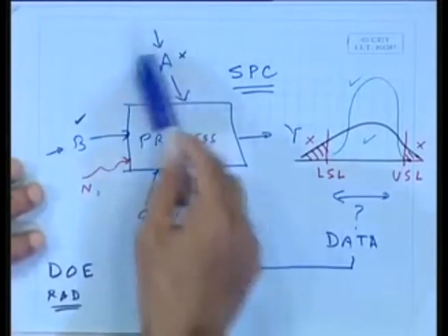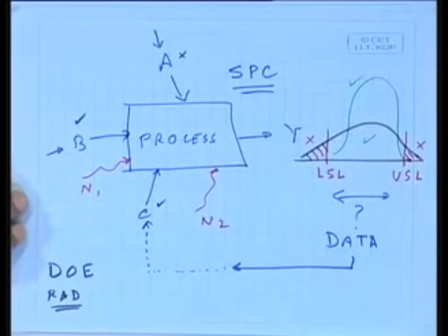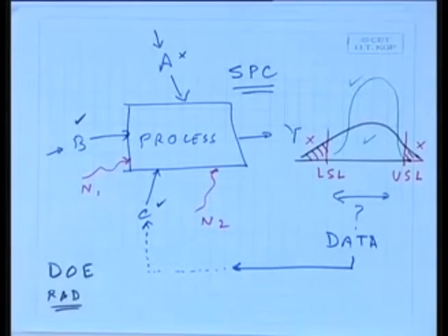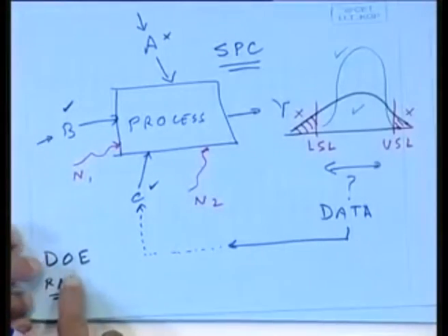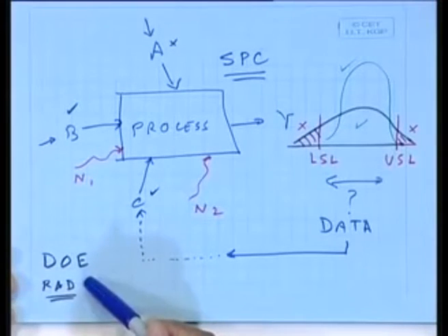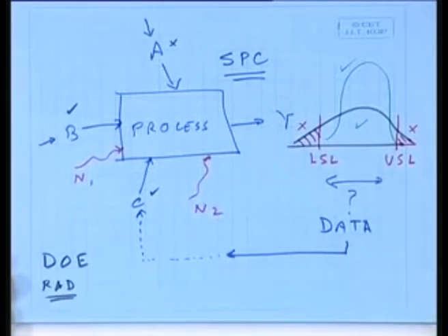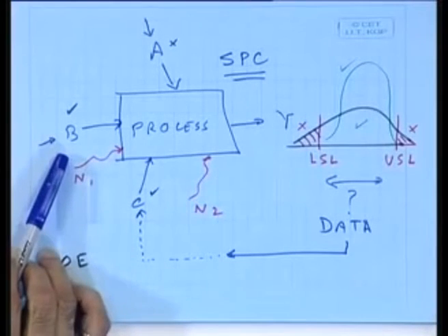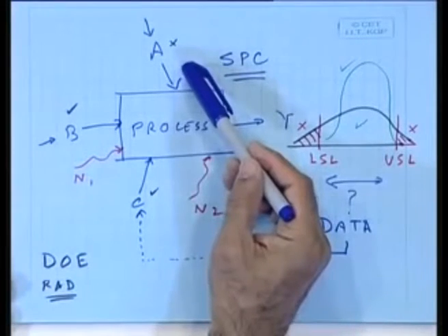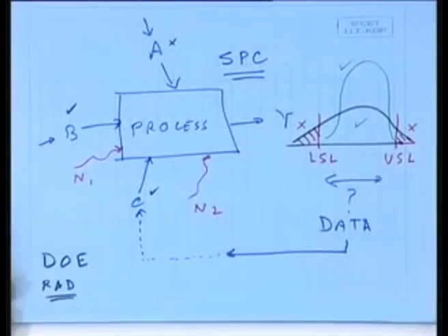There are so many factors influencing this. And if the expert says try to control all the factors, it won't be very efficient. Therefore, I need this technique called DOE to tell me which of these factors really is the culprit. Which is the factor that has the strongest effect, and is there a factor that I can completely ignore when I am trying to really control the process.